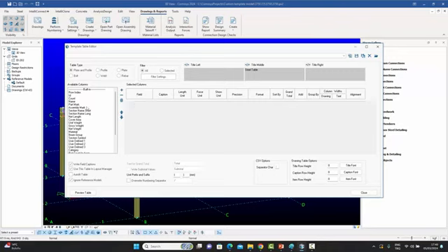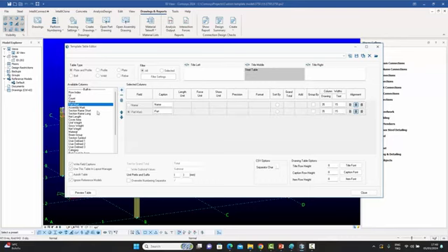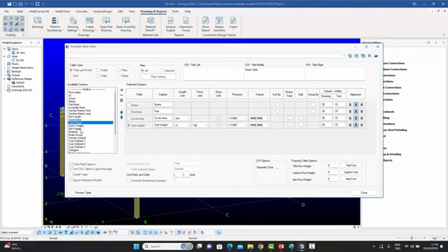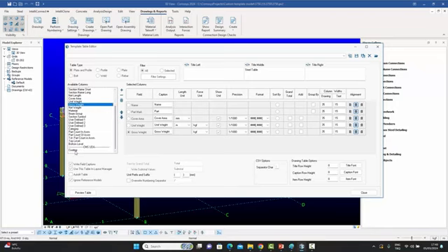And then you can add, for example, if you want the name field to be in there, you can say plus. If you want the part mark, you can say plus. If you want the covered area of that part, you can say plus. If you want the unit weight, you can say plus. If you want the gross weight, for example, you can say plus. And this way you basically create all. And if you wanted, for example, to include this particular user-defined attribute, you can say plus again.